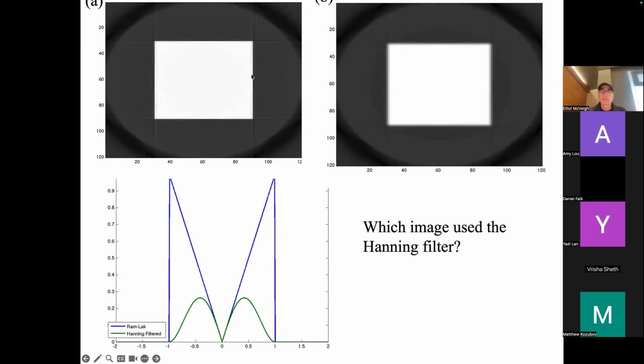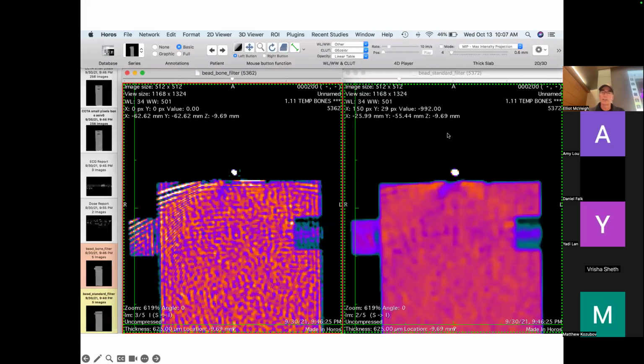And it produces images with very sharp edges and high spatial resolution because you have these high spatial frequencies in your data. However, it can cause noisy images, and so oftentimes what's done is the ramp is modulated, or the coefficients that are way out here are decreased such that they go back down to 0 at the bandwidth of our picture. And that produces a much smoother image and has less noise on it.